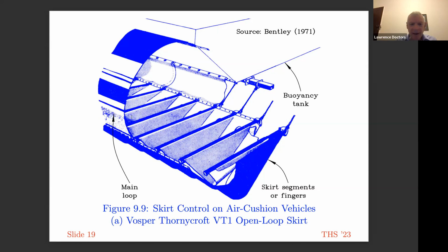It's only the top part of the bag. And for the lower part, you can see internal fingers here. So that means that you've pressurized the whole area here. So you've got a high pressure on the inside of the bag, and then the fingers, of course, are under pressure from the normal cushion pressure.